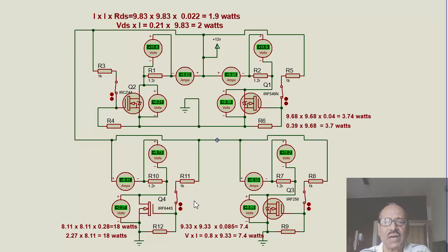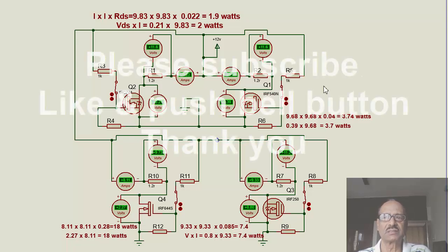So based on your design, what your voltage and current requirements are, you have to choose the MOSFET accordingly. One has to choose based on the voltage and current parameters, and most importantly the RDS parameter. We shall discuss in the next part another important parameter, the gate capacitance. There is a capacitor in the gate of all these MOSFETs, and the value of the capacitance plays an important role too.